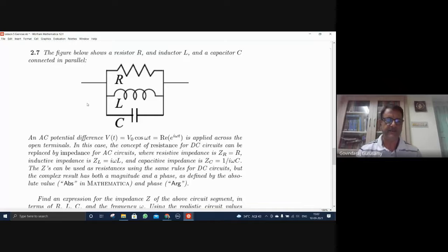Energy will be stored, dissipated, storing, decaying, storing, decaying. That is L and C. If I have an R and C with a DC component, if I put DC instead of an AC, there's going to be a decay. How fast and how slow that decay is depends on the magnitude of R and C. The rate at which they decay will be decided by the product of R and C.